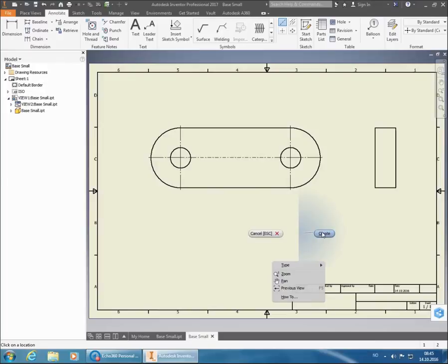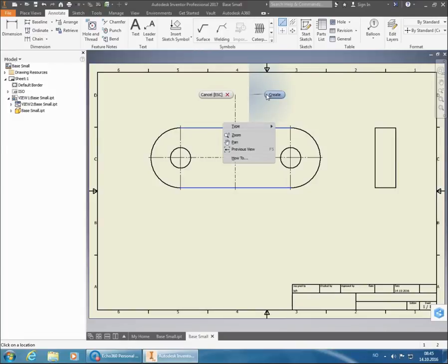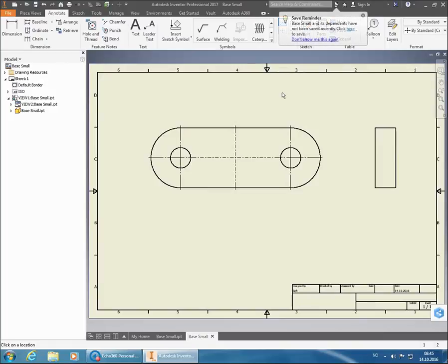And then I need to right click and do create afterwards before I do anything else. Then I'll create another line going vertically through my entire part there, and I right click and do create. If you don't right click and do create, it's going to create a circle and try to do some funky looking stuff. That's because if you have holes that are in a circular pattern, so you have holes evenly spaced in a circle, you can use center line and just pull a line between all of the holes, and it's going to create a nice design around it.